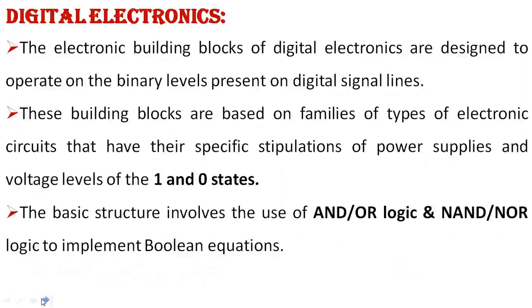Next one is the concept of digital electronics. The electronic building blocks of digital electronics are designed to operate on the binary levels present on digital signal lines. The building blocks are based on families of electronic circuits that have their specific definition of power supplies and voltage levels of the 1 and 0 states. The basic structure involves the use of AND and OR logic and NAND and NOR logic to implement Boolean equations.